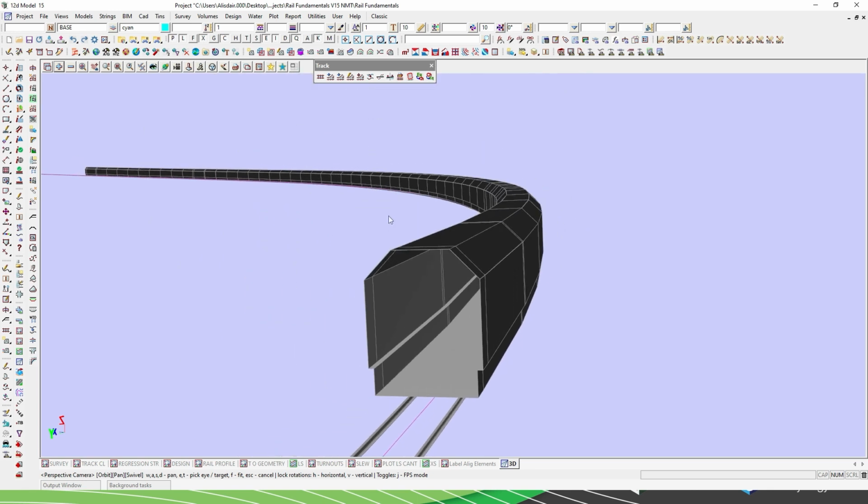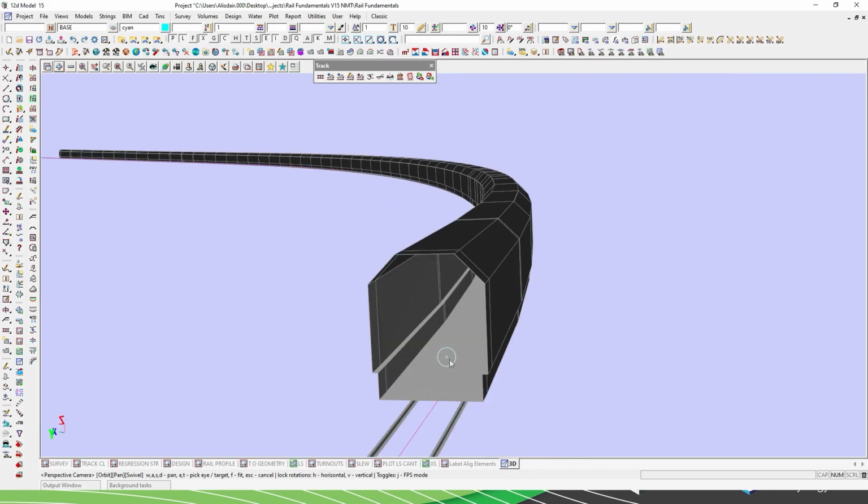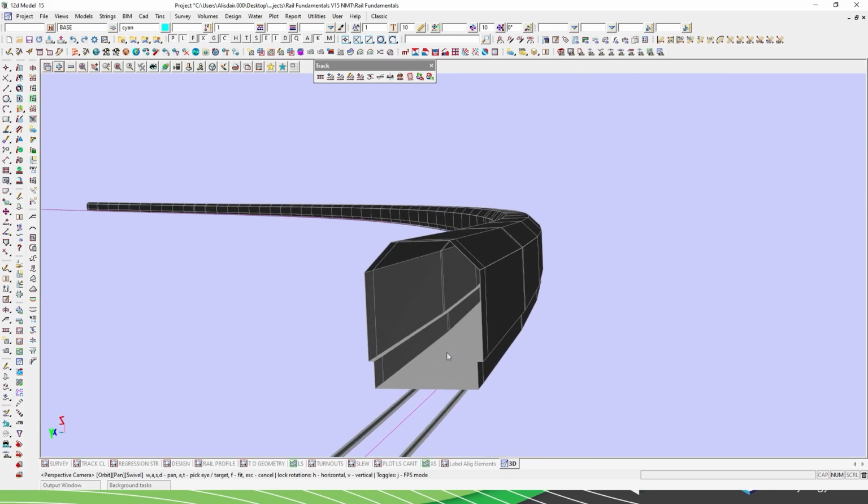training notes. So what we have sitting in here now is a tri-mesh. There is a move afoot to make the tri-mesh have a blend on it, so you can put transparency into it. It's not there at the moment, but it will happen in the near future. Basically, as I said, this in the past was just giving you cross sections. So now you have the ability here to go and create the tri-mesh, which means you can set that tri-mesh directly up to work with your other elements to do your clash detection.